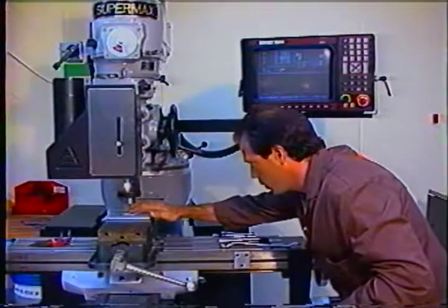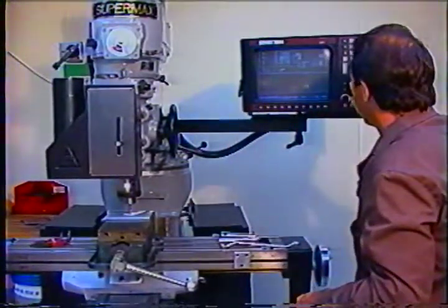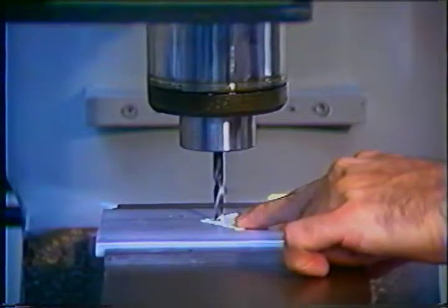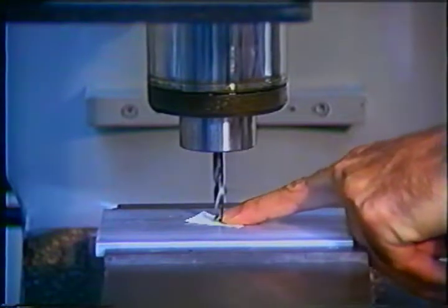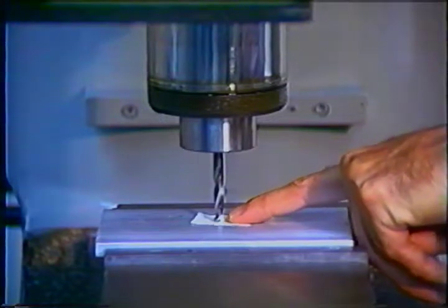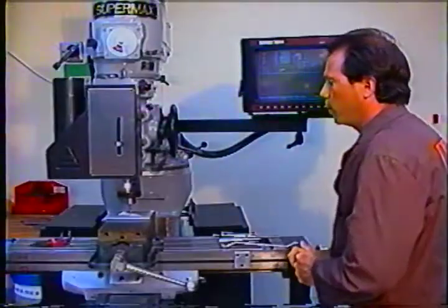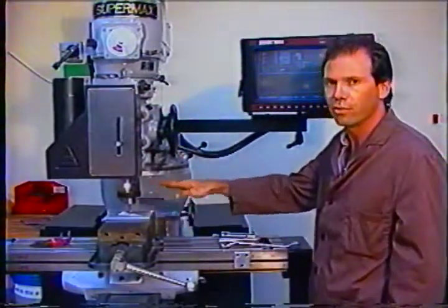set it between the tip of the tool and the top of the work, and jog Z down carefully. I'm going to go 10 thousandths at a time. I can see I still have quite a bit of room. And I'll go down to 1,000th at a time, and I'll jog Z down, moving the paper here back and forth until the paper stops. Paper stops, obviously the tool is touching it. The paper only being a couple of thousandths thick is plenty accurate enough for drilling a through hole.